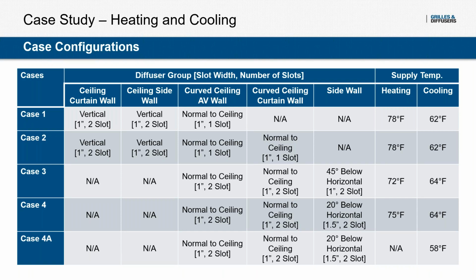For the specific layout, we did 4 different case studies. Between all of the different case studies, we were changing the diffuser placement, the number and size of slots, the supply temperatures, as well as, at the end, some minor pattern adjustments.